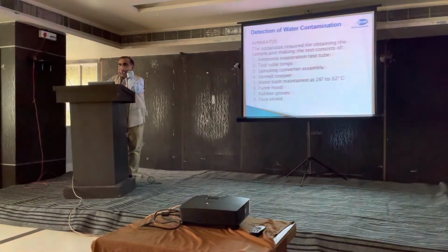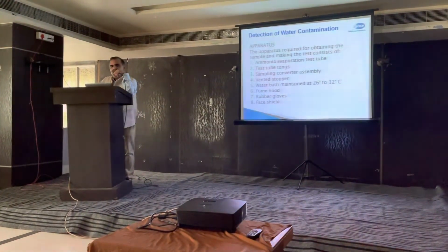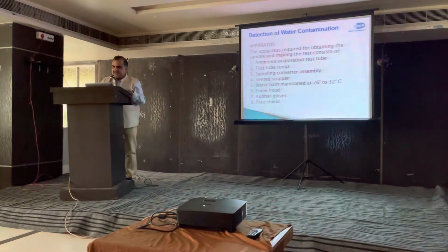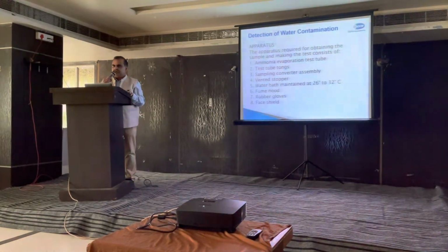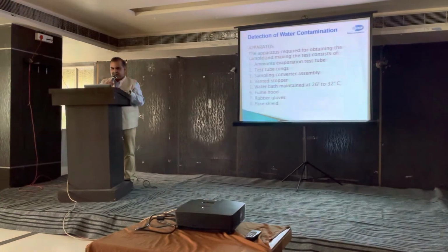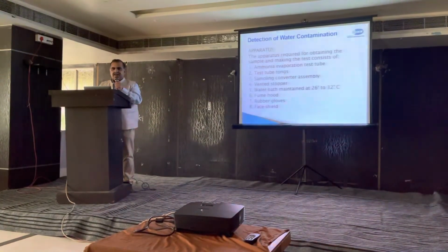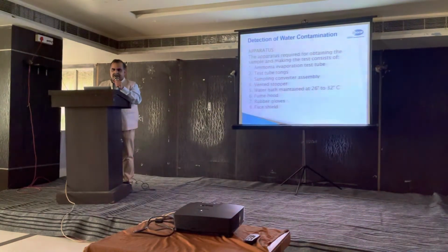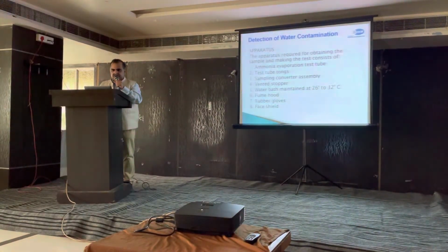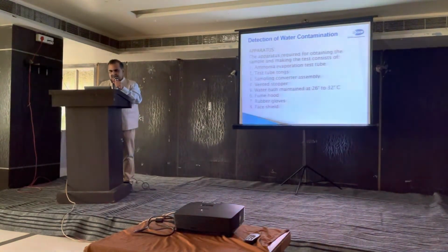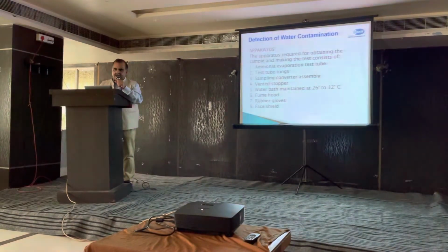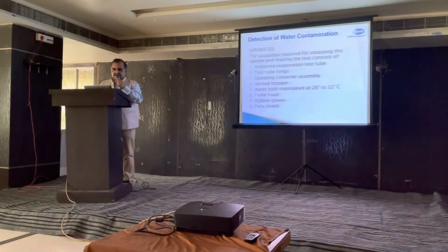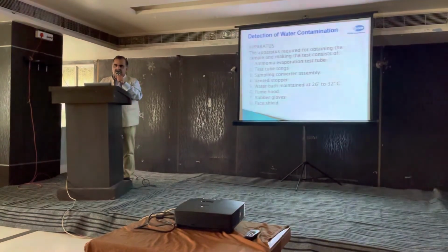So the question comes, can I find out or quantify the water in my refrigeration plant? The answer is yes, we can do that. We need certain precautions and equipment to quantify the water. We need an ammonia evaporative test tube system, and we need to use a PPE kit, hand gloves, and face shield, so that you will not get into trouble.